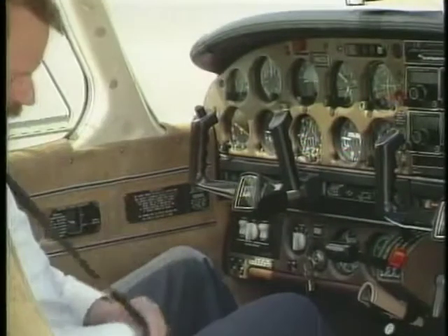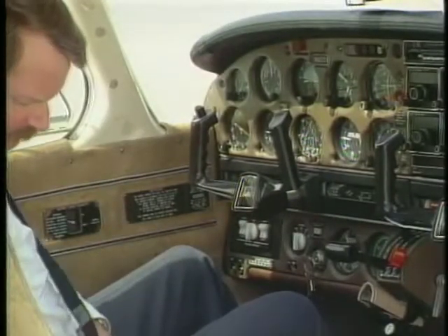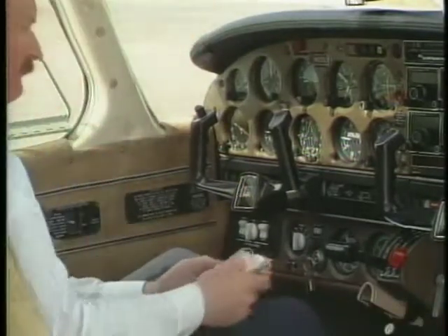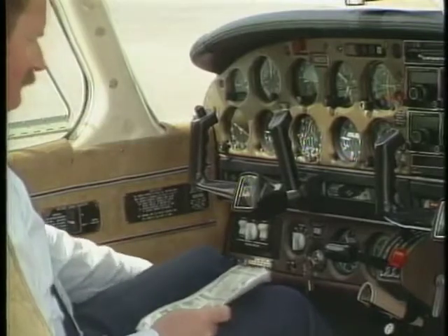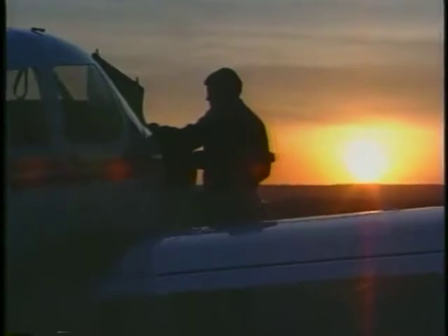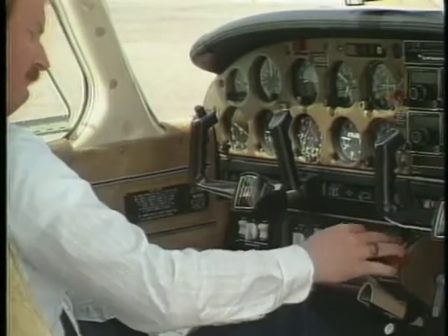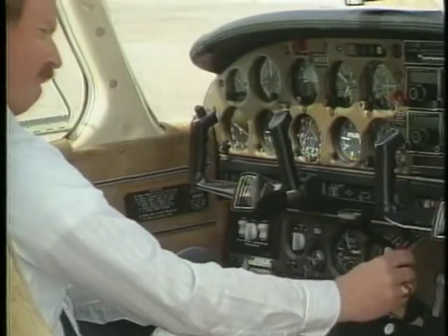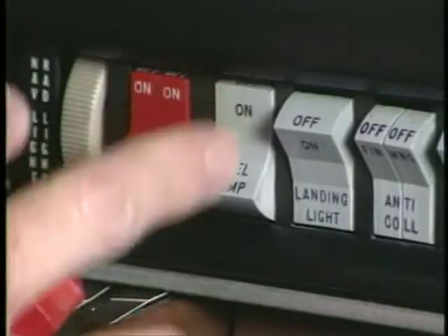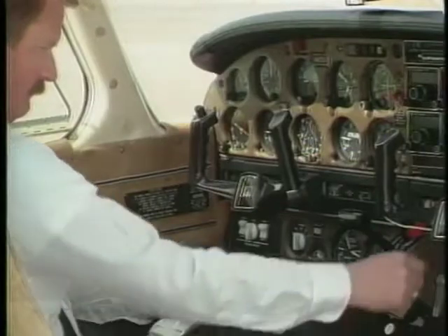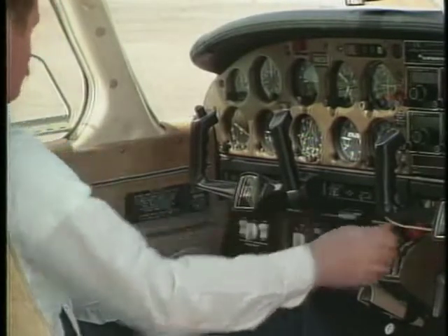The last topic we'll discuss is starting procedures. Although the starting procedures vary between manufacturers of fuel-injected engines, all of them have one thing in common. That is, if the engine is cool to the touch or is being started for the first flight of the day, the system will have to be primed. This is accomplished with the auxiliary fuel pump. With the throttle and mixtures set according to the POH, turn on the electric fuel pump and monitor the fuel flow indicator. When a sufficient fuel flow rate is noted, continue with the specified starting procedures.